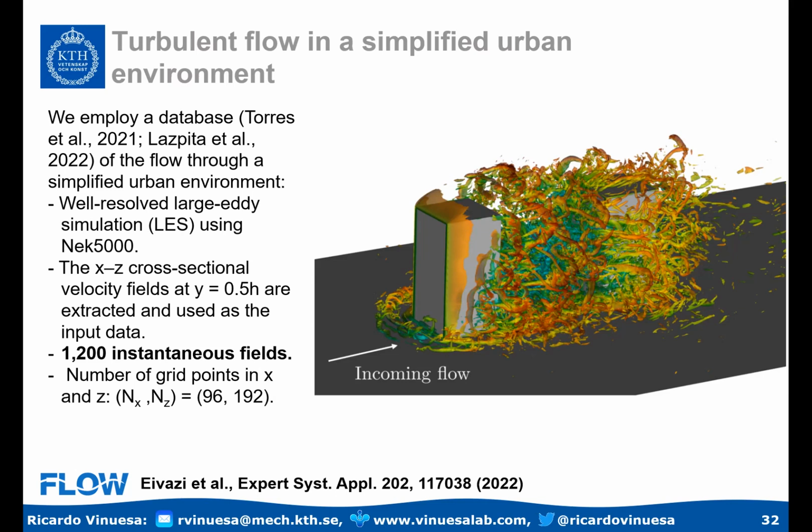If we used a very coarse CFD model to create some sort of new boundary that we kind of know about from the CFD, does that help us understand this area faster than actually simulating the entire thing using a fine mesh model? So you're saying that you want to create a boundary condition from a coarse simulation, and using that you run the finer simulation?